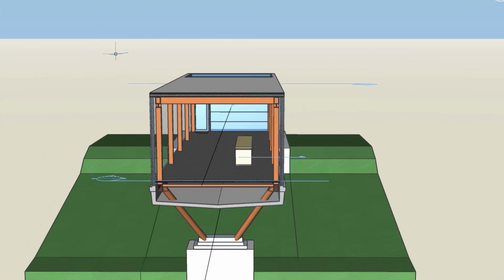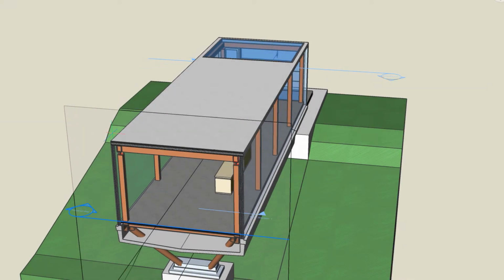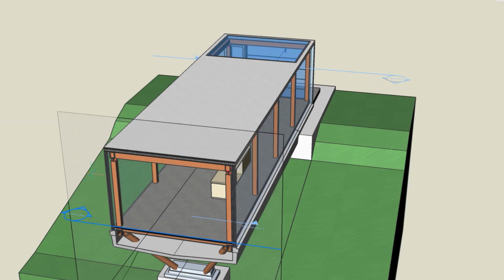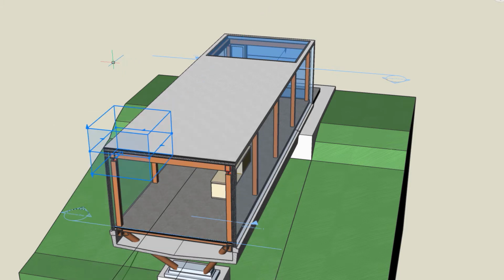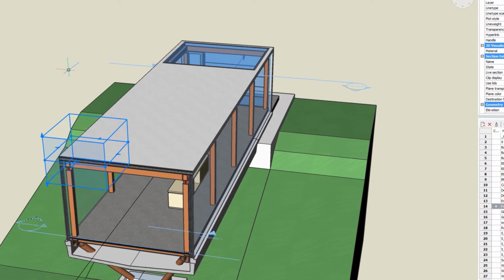To quickly demonstrate the process and how detail can be added, we'll focus on the left wall. Highlighting the section, Detail BIM section is selected, and we'll draw a rectangle for the detail. Next, we add the depth to complete the volume section. Selecting it, we'll adjust a few properties.